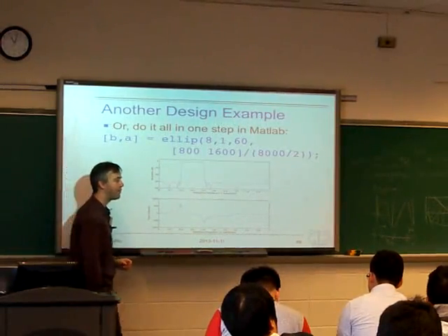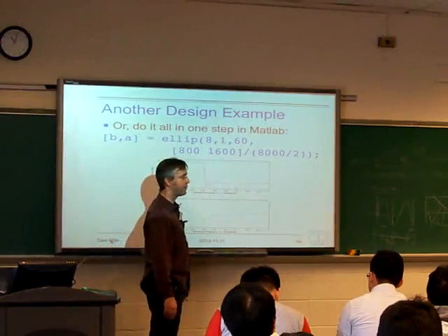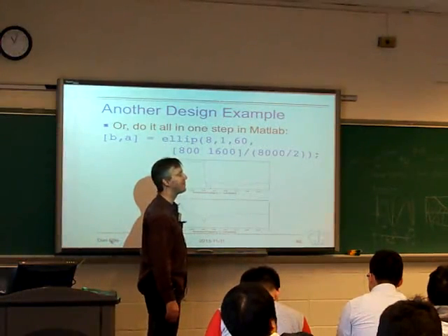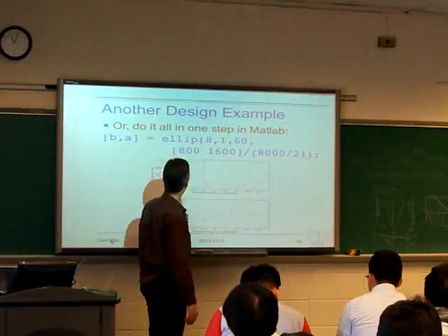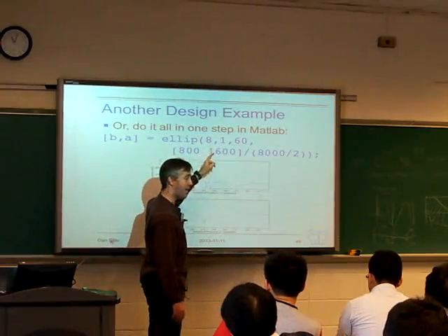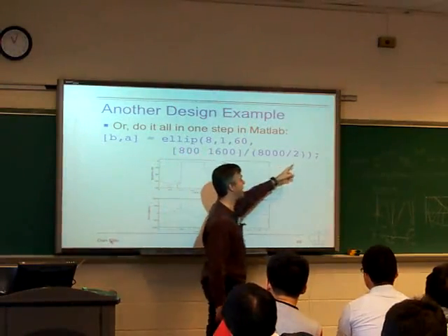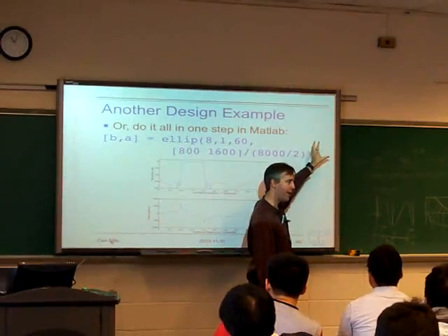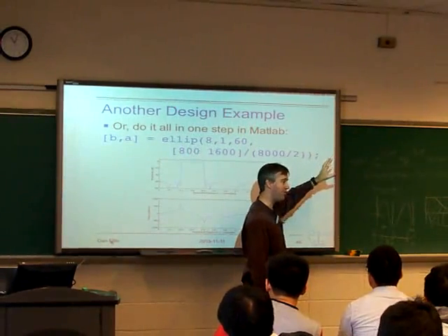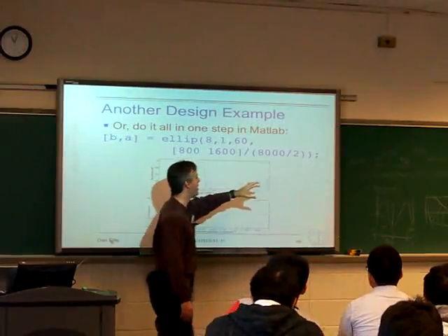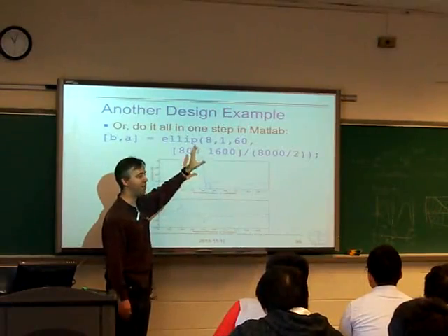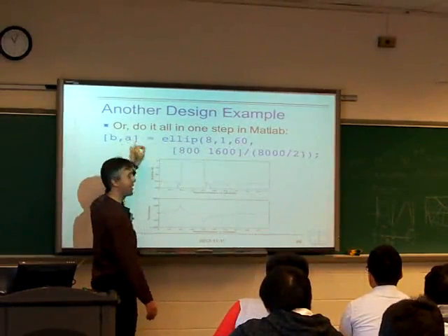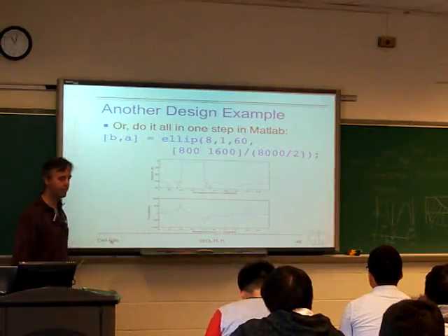Do all the filter functions in MATLAB do it too, like butter? Yes. All the MATLAB filter functions will do this. Oh, and by the way, we used ellip to design an analog domain filter, but we had an extra final argument, which is 's', which just says, oh no, don't do the bilinear transform. The assumption is that by default, you also want to do the bilinear transform as well, so that if you don't say anything, it automatically maps it into the discrete time domain for you.